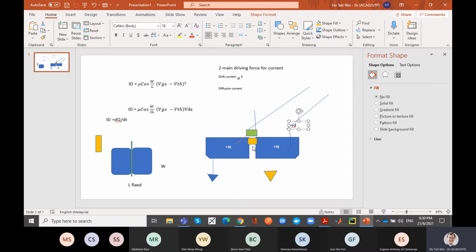In the long channel case, the drift current comes from the electrons traveling faster. That means you're not moving more electrons, you're moving electrons faster. If you double the electric field, you're moving electrons twice as fast. If you quadruple the electric field, you're moving electrons 4 times as fast. So you're getting more current because you're moving the electrons faster, not adding more electrons.